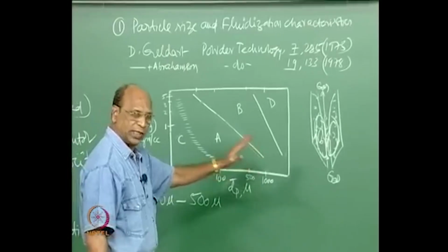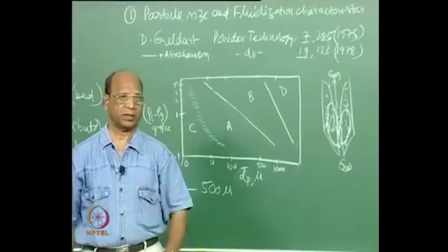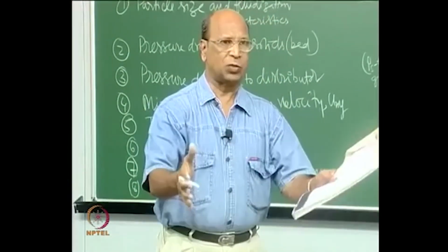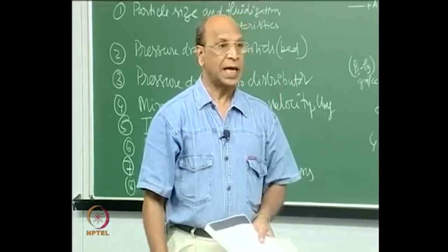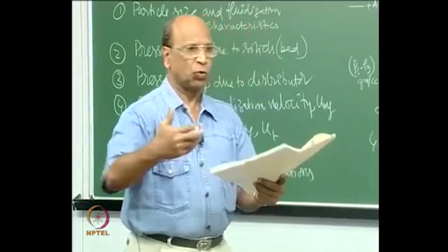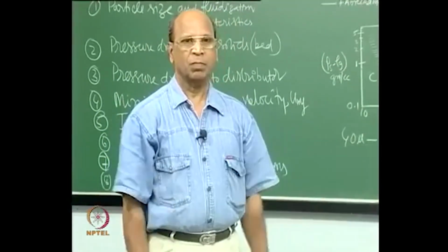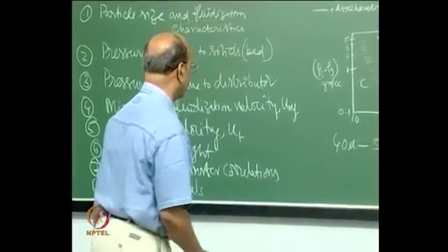We are talking about the case where you want to use a fluidized bed, then go only for a shallow bed. Shallow bed means if the diameter is 1 foot, probably you use only 4, 5, or 6 inches. Then the gas will not have time to become a big bubble, it will easily come out. That is the reason.